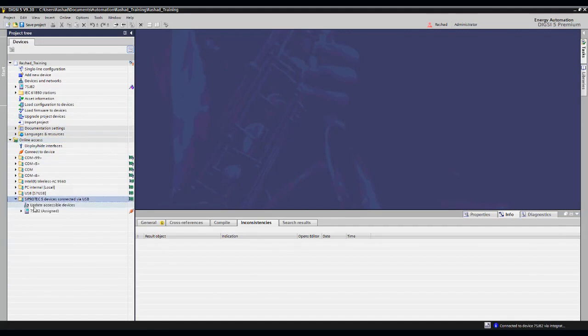You open it and you tell it to update accessible devices. After you tell it to update accessible devices, it will immediately show you, of course I clicked on it before, which device is assigned or communicated with you and will give you the communication icon. So you will open your relay, and inside your relay you will find a set of menus. You want to know what these are about, so quite simply, the first thing you have is something called Open Browser.